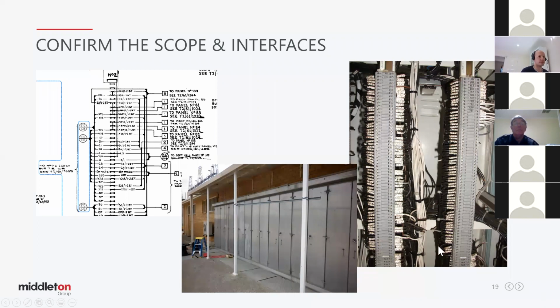What it looks like from the internal, in terms of cables running in, cables running out, typically you'd have field cables on one side, cables that run into the control room on another side, and again you'd split that via redundancy, so you might have an X and a Y strip, depending on what's happening. And then that on the left is how it translates to drawing form.